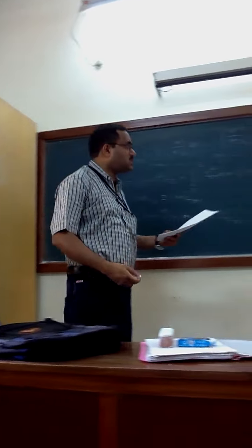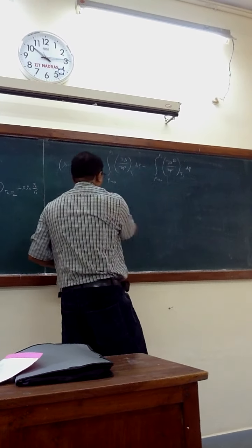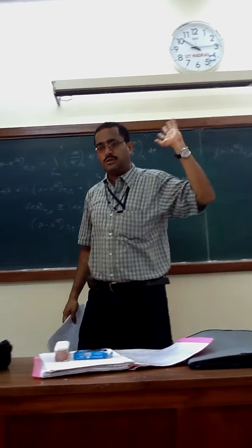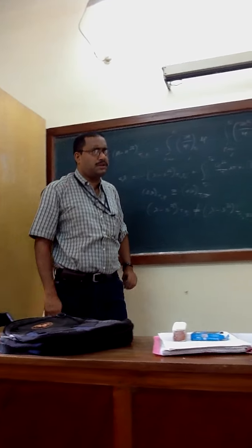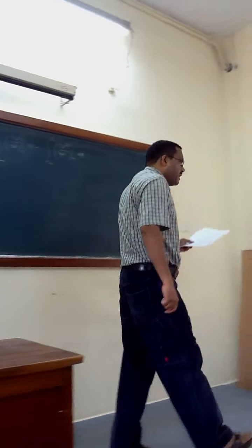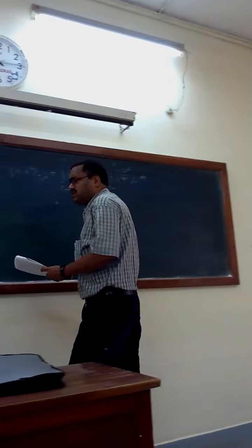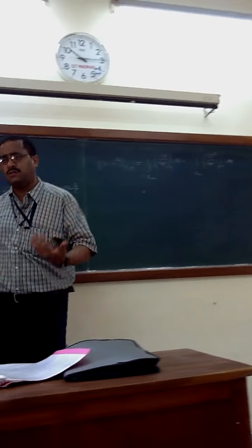No need to think much. And ∂S/∂P at Ti, next step. This expression was there earlier. What is ∂S/∂P at fixed T? It was in the Maxwell's relationship, right? It is minus ∂V/∂T at fixed P. It's Maxwell's relationship. If you don't remember, look back on your notes.